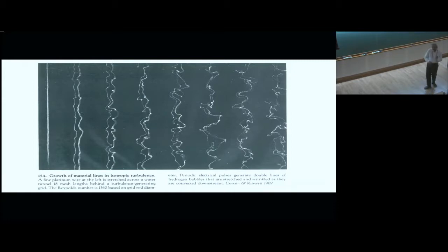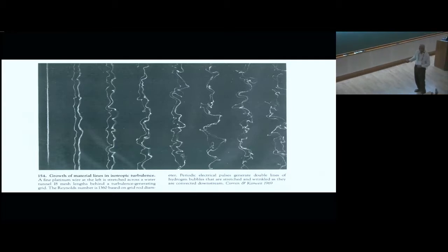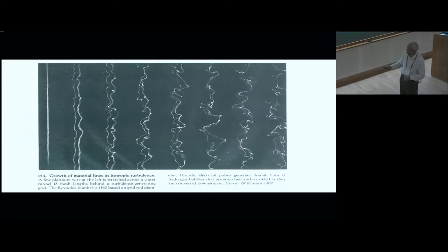And the point about interpreting the flow, you can see from here, the shape of this wrinkled line is essentially an integrated effect of what has happened from the start of generation of the bubbles till that point. So you cannot really say this flow is turbulent, because the turbulence, if it had existed only here, it would have wrinkled the line. But if the turbulence, for example, has died here, it will be non-turbulent flow, but still this wrinkled effect would exist because of what has happened in the history. So that's why one has to be careful in interpreting these various techniques.